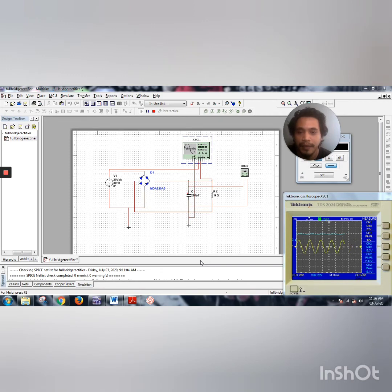My name is Azwar Hakimi, and today I'm going to explain about the full-bridge rectifier. This is the full-bridge rectifier circuit. It produces an output of current which is purely DC, so from AC to DC. In the full-bridge rectifier circuit, the average DC output is higher than the half wave rectifier. It also has much less ripple and produces a smoother output waveform.